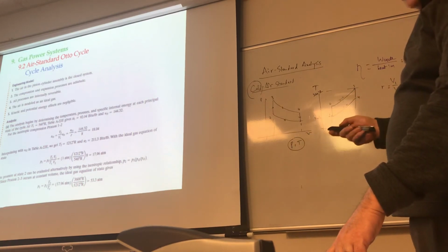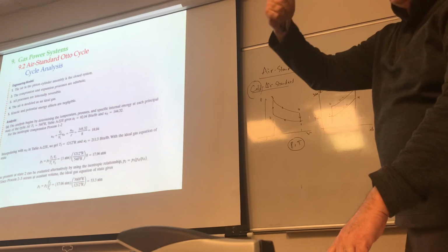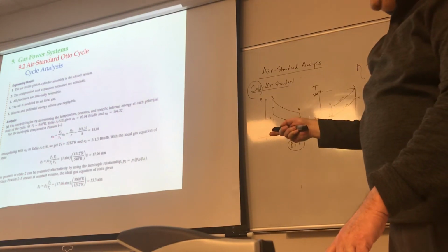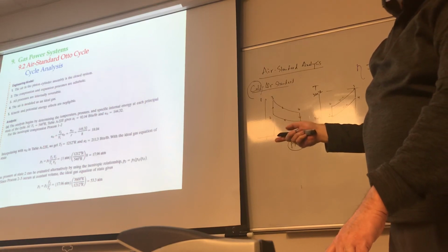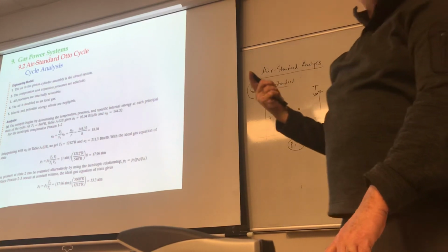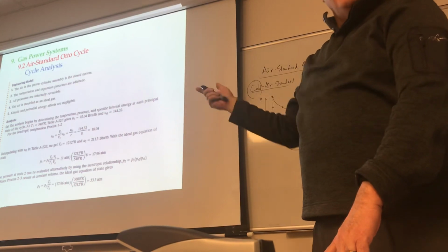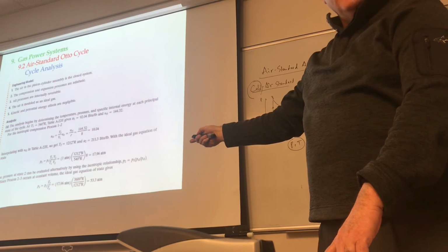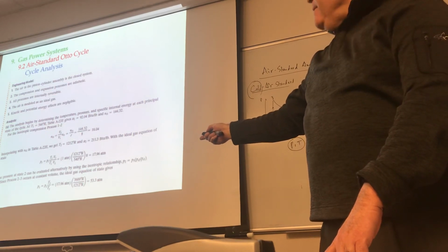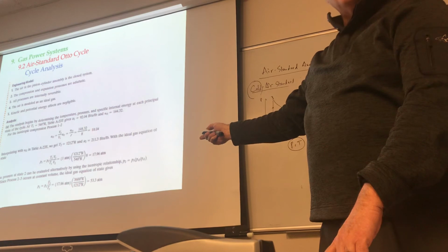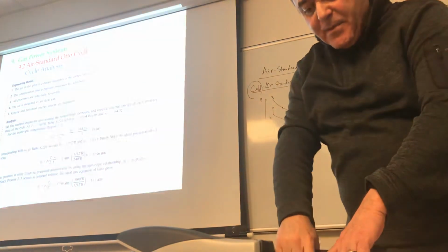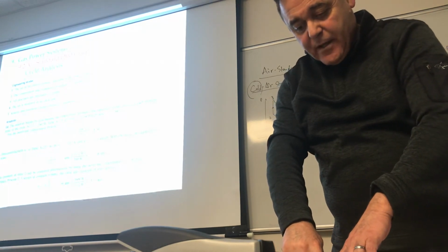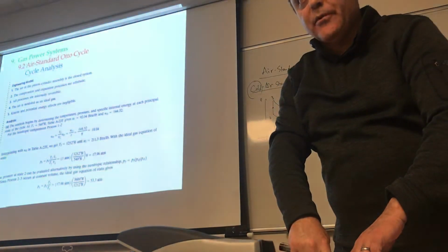And we know that vr2 over vr1 is equal to v2 divided by v1. V2 over v1 we already know. Vr1 we read from the table, that means we can calculate vr2. When we calculate vr2 we find 18.04. Then what do we do with it? We're still on that same table. We try to look for a value where vr is equal to 18.04.